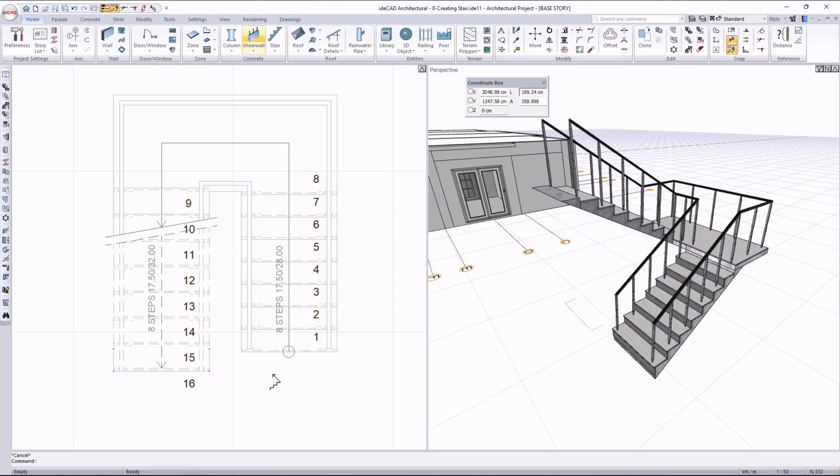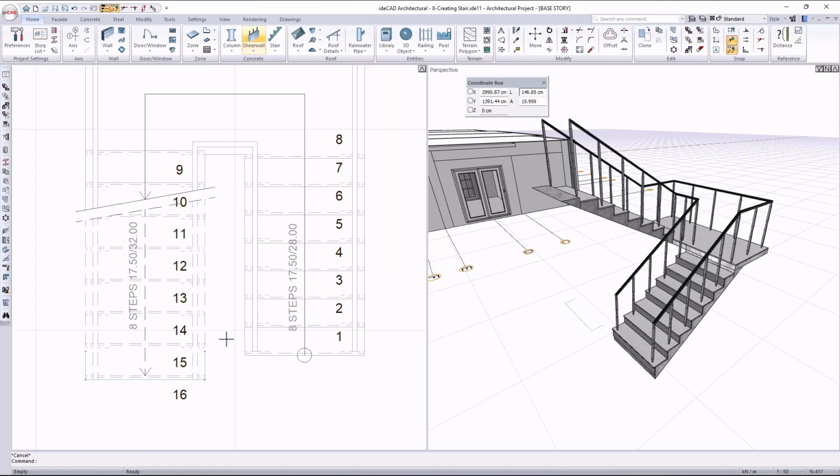After the operation, the stair's information label is updated to indicate that the stair now includes treads with different widths. For example, one segment may display a tread depth of 28 centimeters, while the other shows 32 centimeters. This variation occurs because the stair flights have different lengths after the deformation. To maintain the overall height and fit the geometry, the software automatically recalculates the tread depths for each segment. However, this outcome is not ideal.